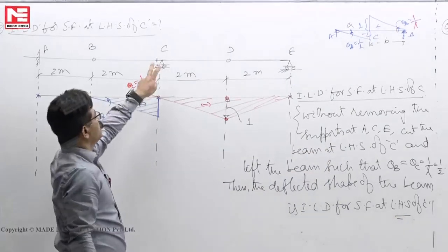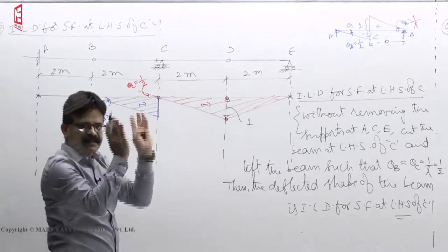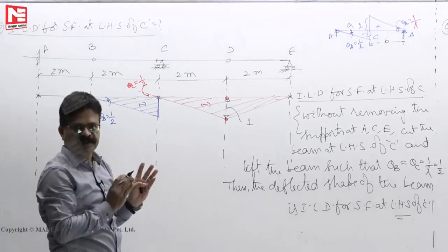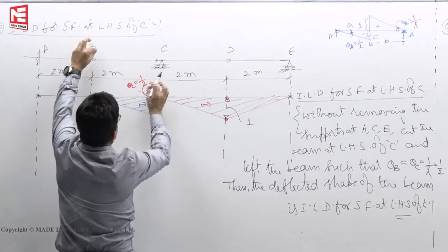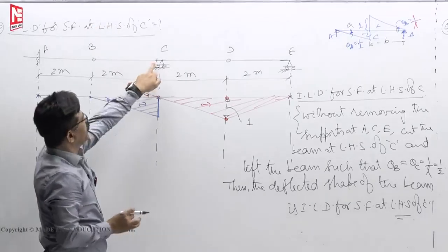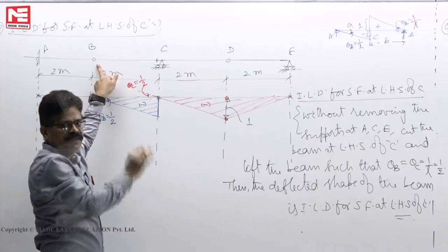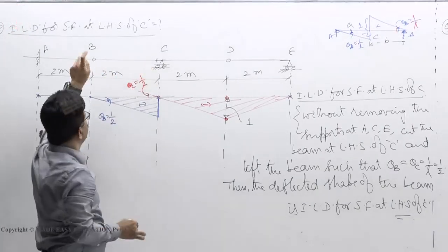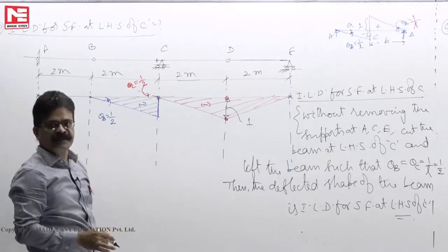So, what you have to see is where you are cutting. That span, how does it behave? Will it behave like a cantilever or simply supported? Accordingly, you have to see. After cutting it, this can only rotate, this cannot be lifted. The supported span you are cutting here, observe this end. Can this end move up and down? If it moves up and down, it behaves like a cantilever. If it cannot move, it behaves like a simply supported span. This way the displacement will be.